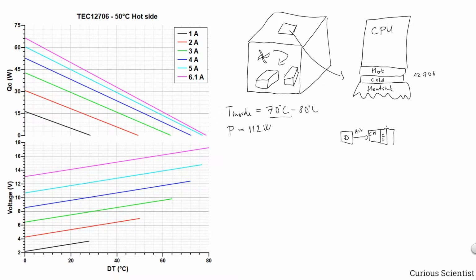Then as you run the Peltier cooler, you transfer the heat from the cold side to the hot side, the HP, the hot side of the Peltier unit. But here you cannot stop, because you have to remove the heat from this, otherwise everything will just overheat. So let's say that now we have our CPU cooler here. That's how the heat travels in a very simplified way.